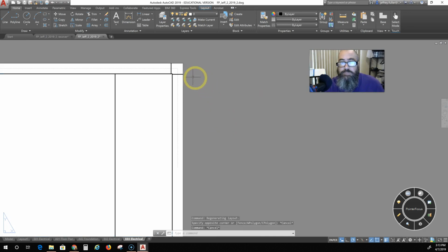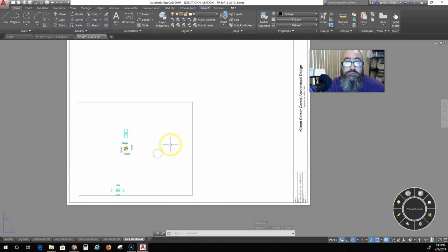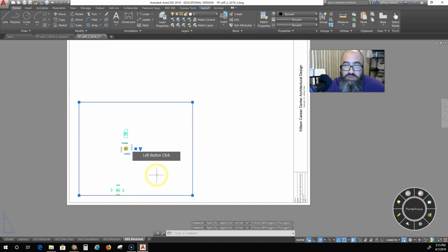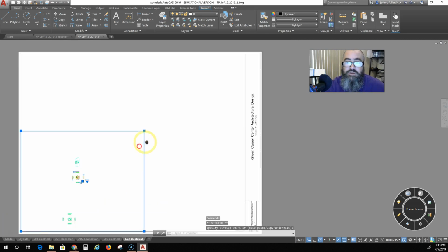We're good. All right, then I'm going to get rid of these lines. Leaving little guidelines like that attached to your drawing is one thing that can make it look very imperfect. Okay, so now my title block is on, and I want to take my viewport. I'm going to select my viewport, and then I'm going to match both opposing corners up with my title block.